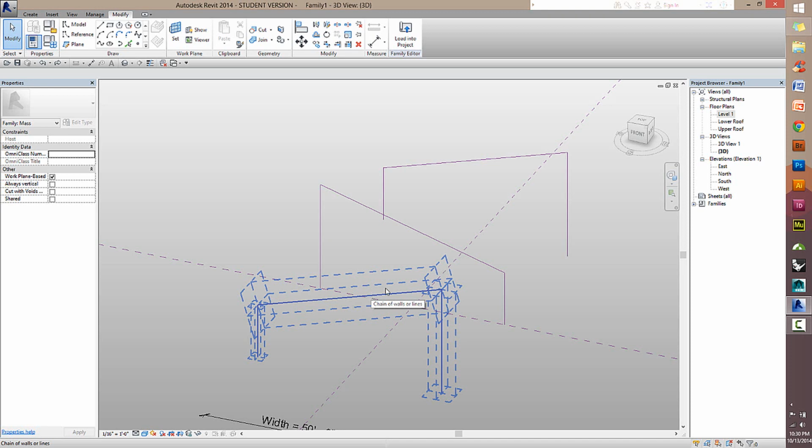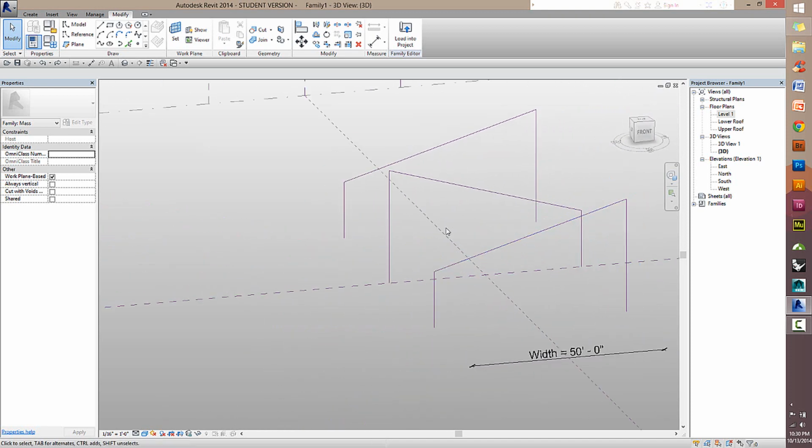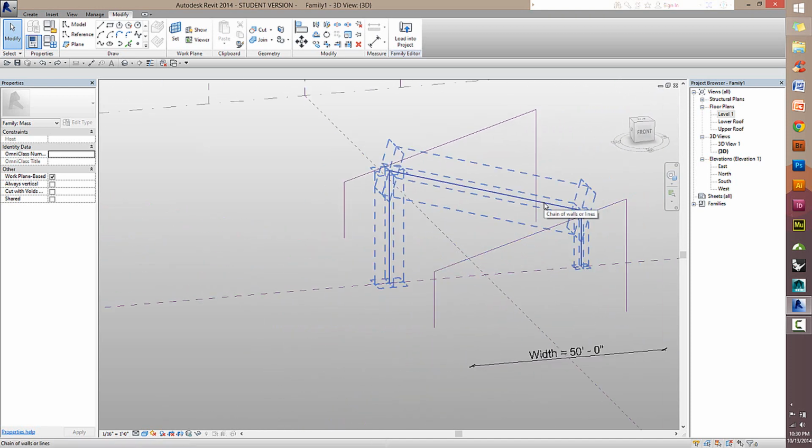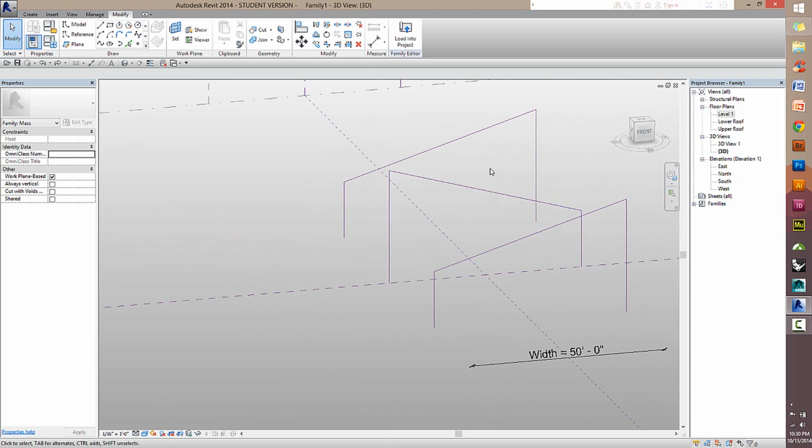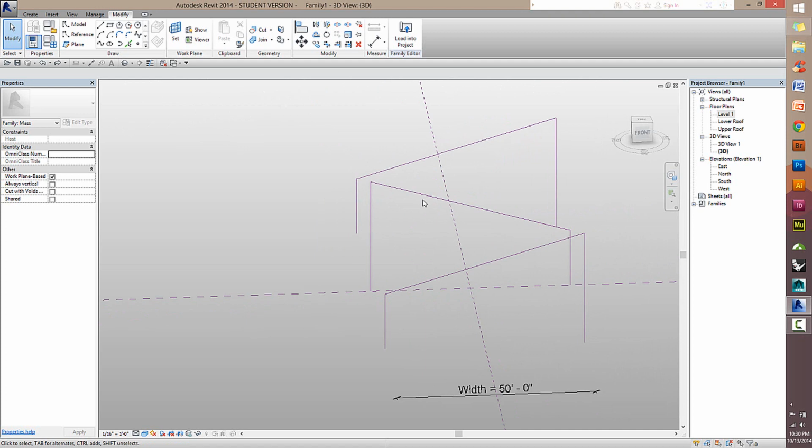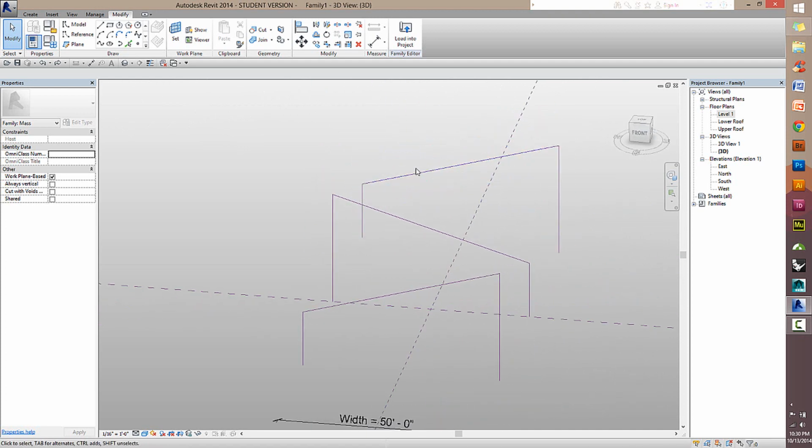To do this, we're not going to create the walls yet, because this conceptual massing environment is really only being used, at least I would only use it, to create the structure and then the basic forms that I could bring into a Revit model to turn into something more meaningful, more architectural, if you will.